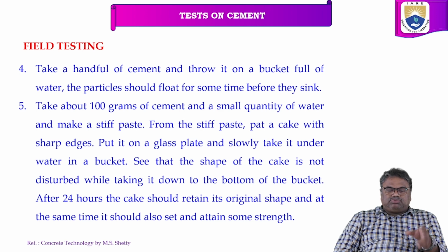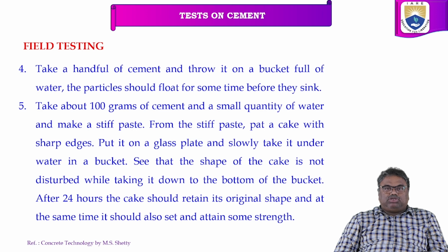Take 100 grams of cement and a small quantity of water. Make a stiff paste. From this stiff paste, pat a cake with sharp edges. Put it on a glass plate and slowly take it underwater in a bucket.